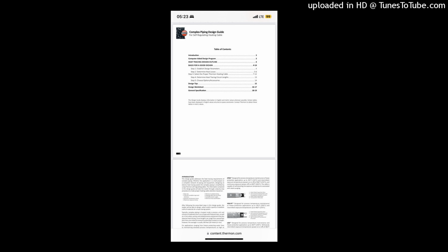Minimum startup temperature. This temperature differs from the minimum expected ambient in that the heating cable will typically be energized at the higher ambient temperature. This temperature will have an impact on the maximum circuit length and circuit breaker sizing for a given application. See circuit length tables on pages 8-12.